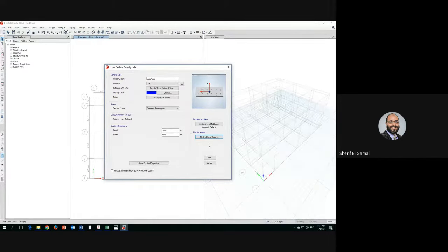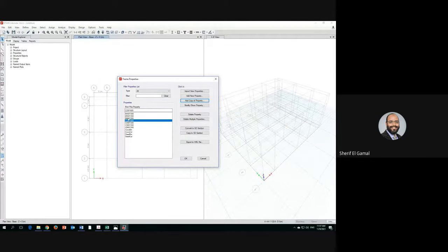So you can see now you have this column. You can put it directly. If you want a horizontal column, you can use this one instead of putting vertical and changing the direction. It's up to you. Let's say now what we defined: some beams, 400, 500, 600, and columns 200 by 600, and 400 times 200, 500 times 200, 600, and so on. So these are the columns.